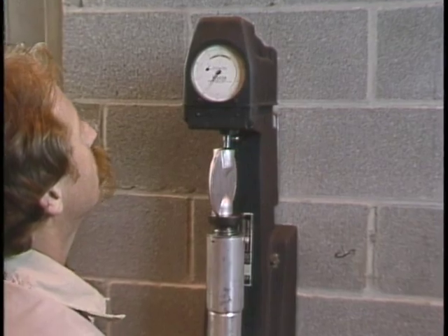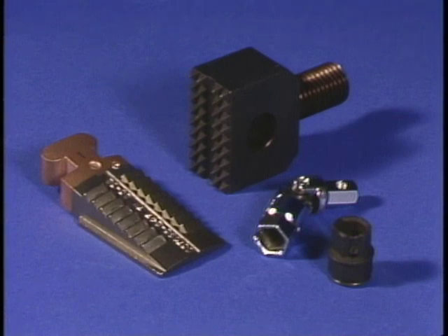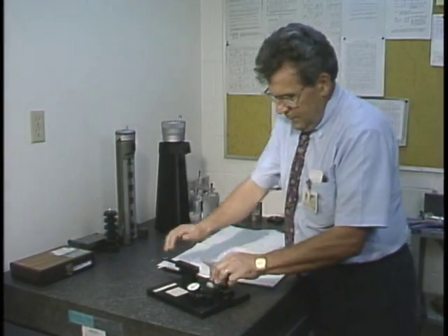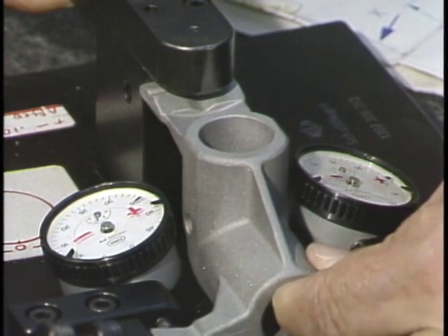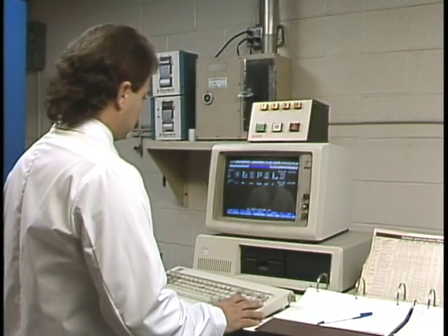Heat treatments are often used to enhance physical properties, and other options frequently improve the already fine finishes of the investment casting. Some parts require careful gauging for possible distortion, and representative samples of every run are carefully checked by quality assurance for strict conformance to specifications.